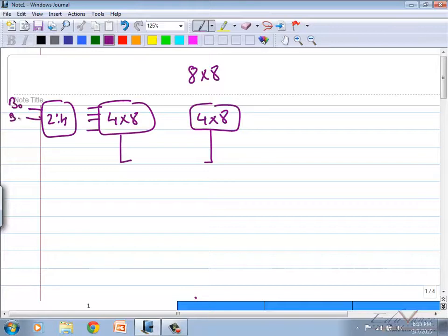What I will do, bit 0, bit 1 and bit 2. The MSB I will use for controlling column decoding. Understood? Yes or no? The MSB I will use for column decoding. Obviously, the first 4 locations will be stored here: location 0, 1, 2, 3.